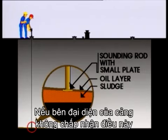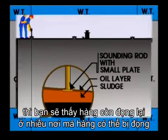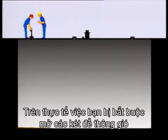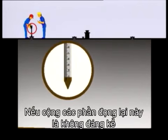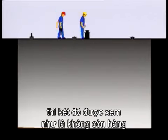If the representatives from the terminal don't accept this and force you to open the inerted tanks to the atmosphere, you should dip the tank in as many positions as possible. The fact that you are forced to open tanks to the atmosphere should be noted in the ship's logbook, and a protest should be filed. The results, as well as positions dipped, and the time must be carefully noted. If these additional dippings don't show any volumes left, the tank should be regarded as empty.